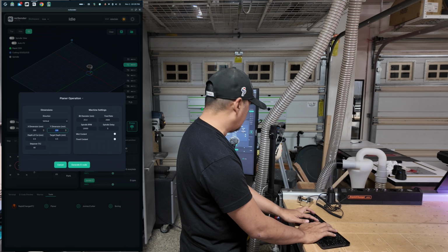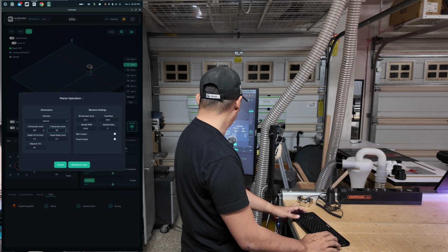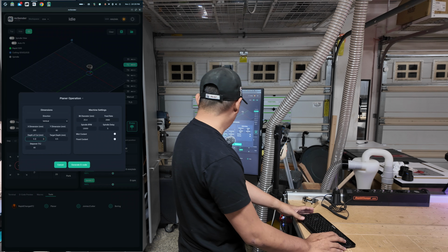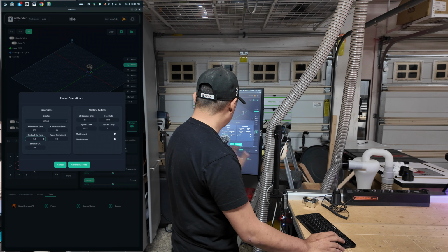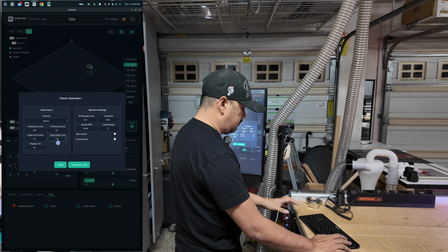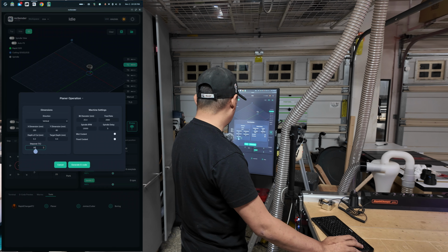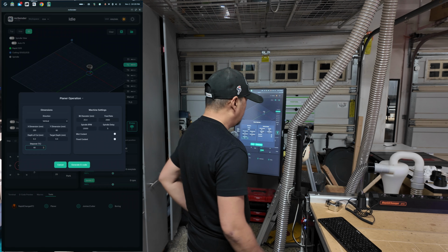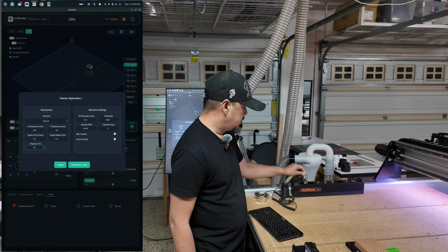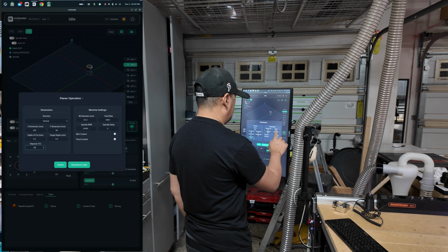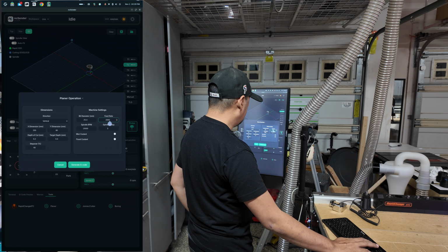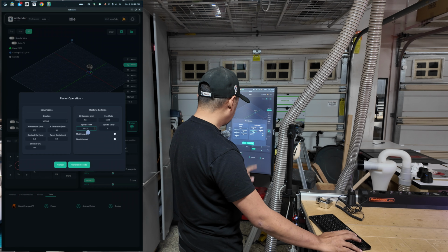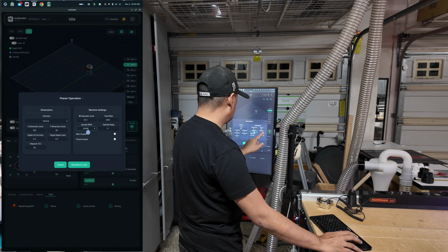And then 75, or let's just make it 80. Then depth of cut, I only wanna do maybe 2. And then target depth, maybe 0.4, so it's 2 pass. Step over is 80%. Let's just do 60%. Then the bit I'm gonna use is a 1-inch surfacing bit. My feed rate is maybe 1,500 for now. RPM is 1500.